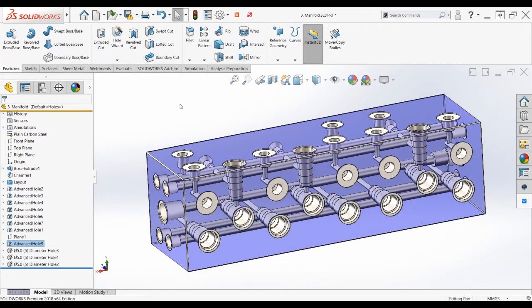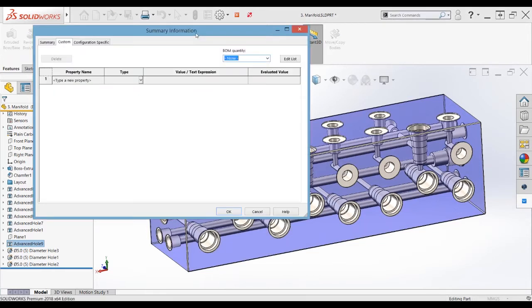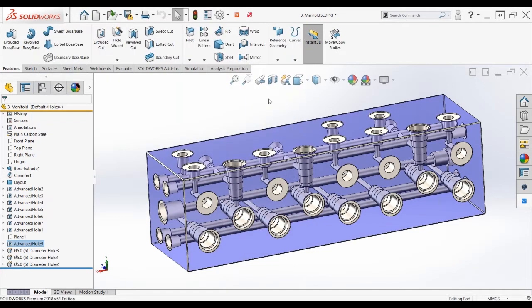So speaking of my drawing, this part file needs some file properties that we're going to automatically propagate in the title block of my drawing. But I'm looking at my file properties and it's empty. So maybe I accidentally chose the wrong template that didn't have it in there, or people are putting in spelling mistakes or incorrect formatting, and it's not lining up really nicely. A good way to standardize your file properties is to use the property tab builder.